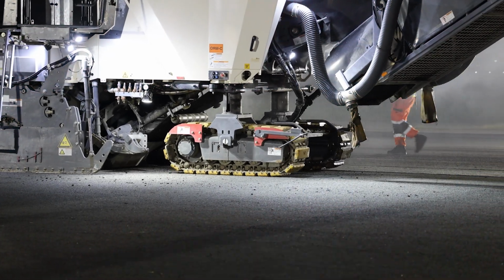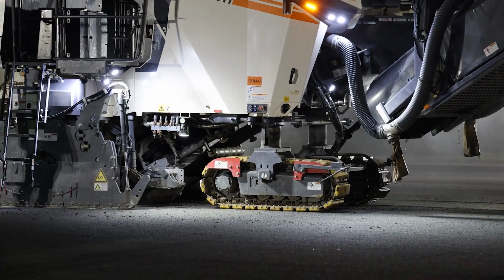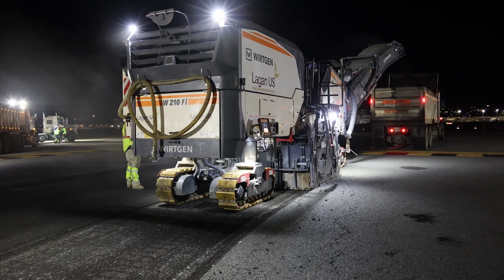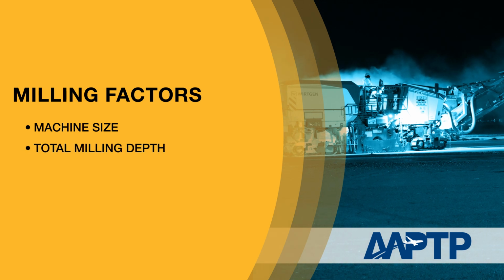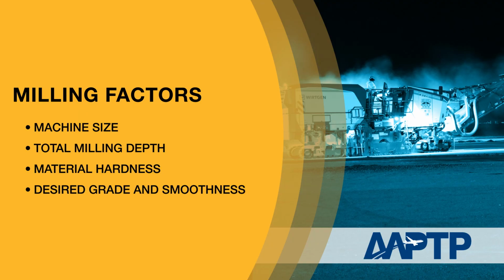Choosing the correct milling depth is crucial for quality, productivity, and project cost. The designer specifies the total milling depth required to remove pavement distresses and achieve proper grades. The contractor then determines the number and depth of milling passes based on factors such as machine size, total milling depth, material hardness, and the desired final grade and surface smoothness.